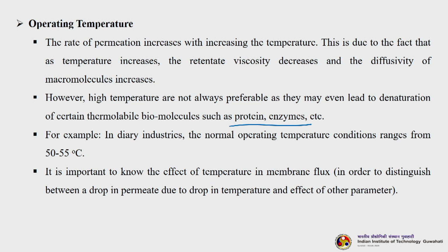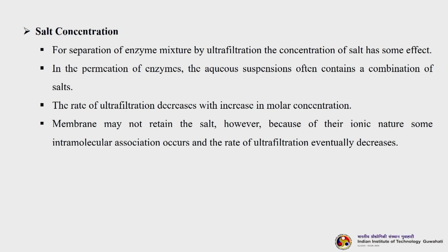Now, it is important to know the effect of temperature on the membrane flux in order to distinguish between a drop in permeate due to the drop in temperature and the effect of other parameters. The next is salt concentration.